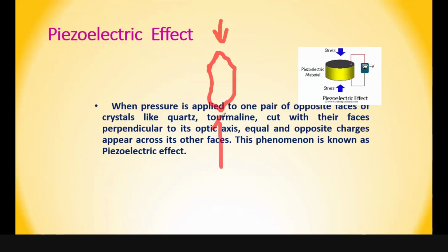It can be compressive or tensile, stretching stress. So suppose I am applying force on this piezoelectric crystal, at that time opposite charges will be developed on the two faces of the crystal. One side will be positive, one side negative. So this effect is known as the piezoelectric effect, right?